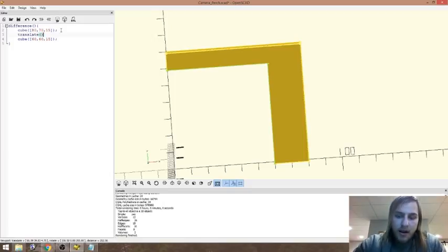This time we are going to have arguments for this command, and that's going to be in the square braces. You want to move it over 5 millimeters in the X direction. So we just type 5, 0, 0. Now also, we need our curly braces. And I'm going to push tab here to keep our syntax looking pretty.